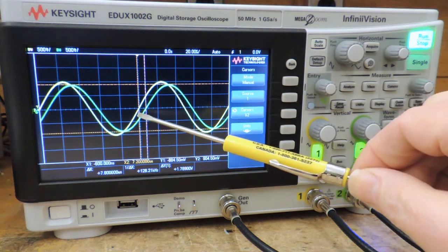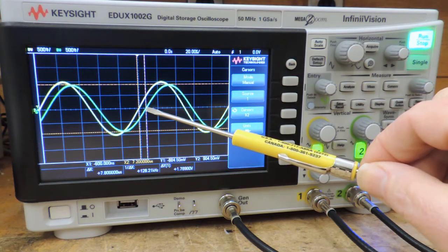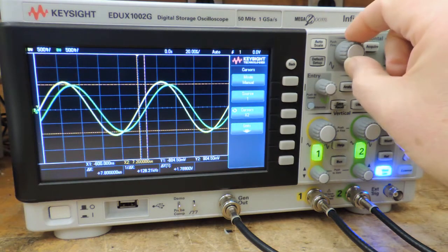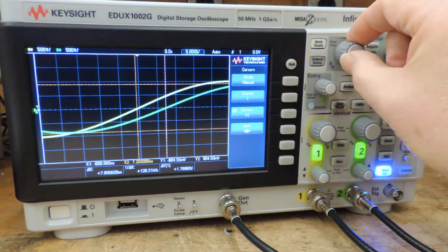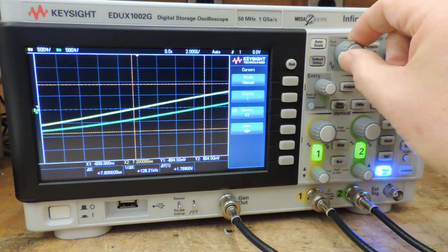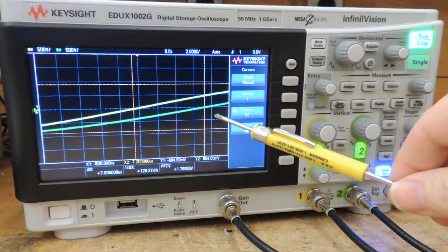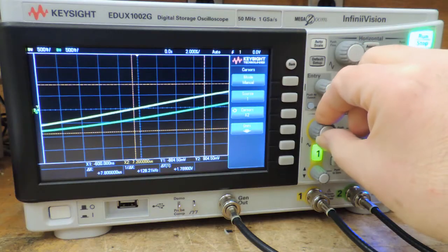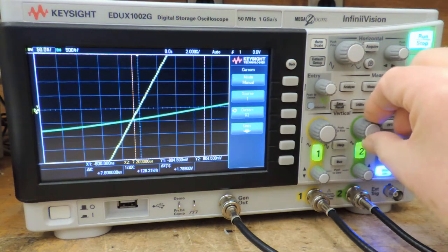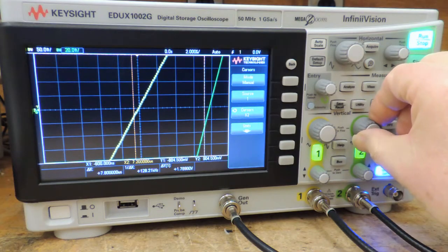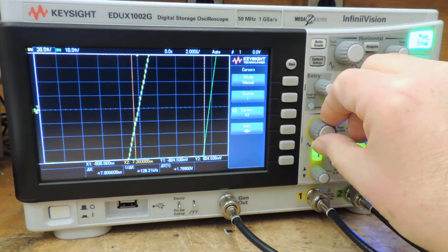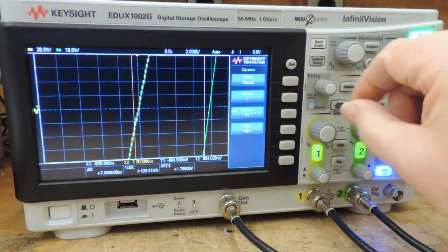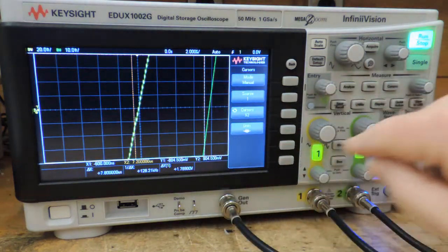Now it might be hard to see exactly where those 0 crossing lines are. So what I do is change my horizontal, so I actually open up the waveform. Now it will go off the screen, but all I'm interested in is these 0 crossing points. The next thing I do is change my amplitude, so I want to get the waveform crossing vertically. Now it's gone way off the screen, which is perfectly okay, but all I'm interested in is those 0 crossing points.